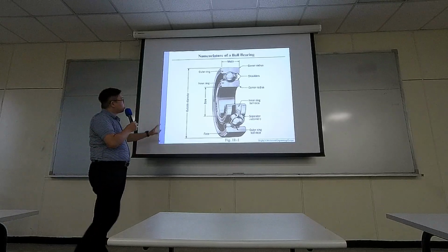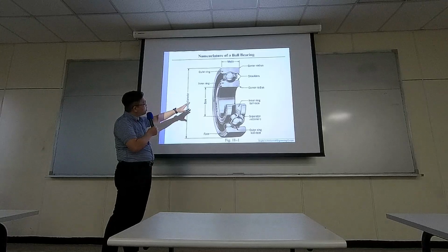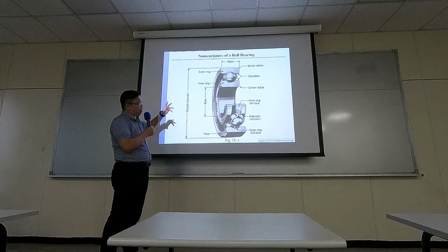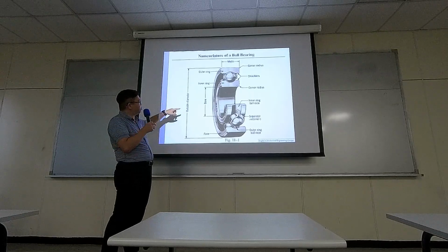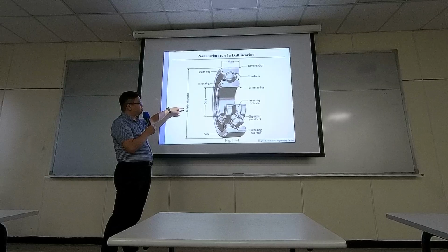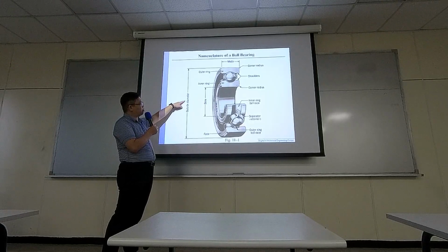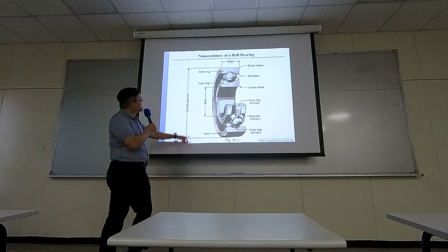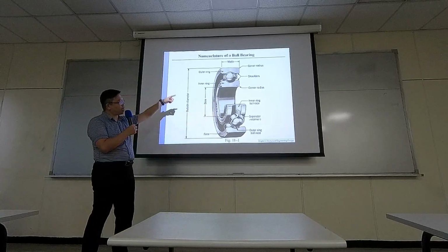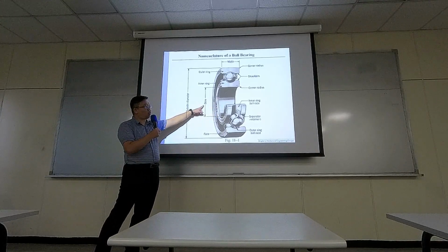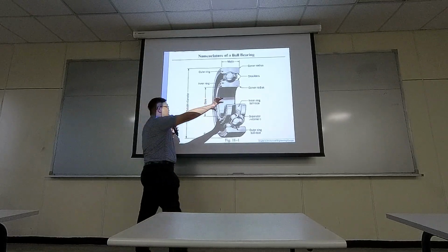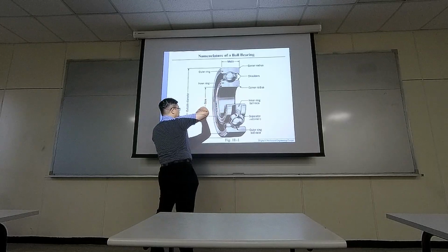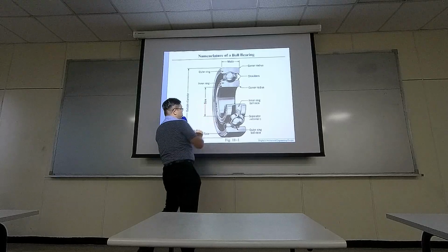So usually when you buy a bearing, you care about the dimensions. The outside, in some catalogs, will just say OD, meaning the outer diameter or outside diameter. Okay, and the inside, the inner diameter, is usually called the bore. Usually you have a shaft design. You should design the diameter of the shaft to match the dimension of the bore.